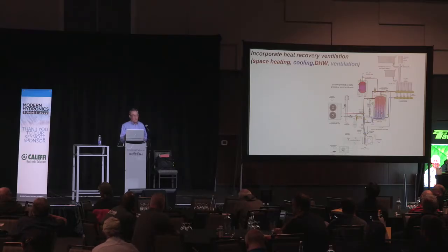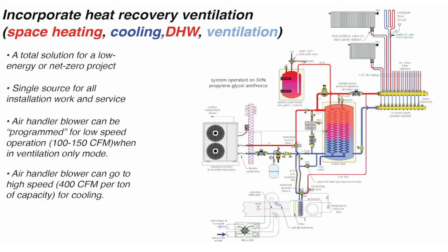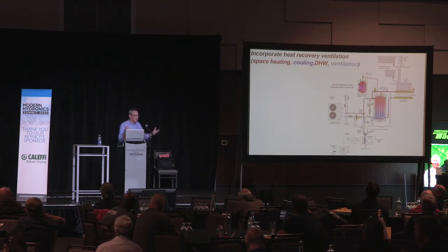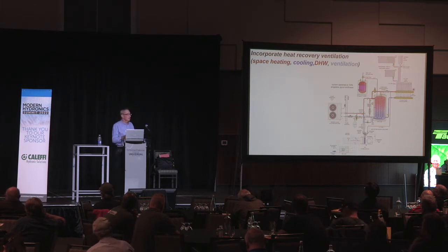The other thing that you'll see over on the far right side of that manifold, and I'm a big believer in promoting this, I always like to see at least one extra connection pair on a manifold station. So five years from now, maybe they might say, well, I want to add a towel warmer to this bathroom. You've got the connections, all you've got to do is isolate the manifold, bring in the PEX to the towel warmer, connect it, and you're back in business. If you don't put those extra connections in, you can still do the work, but it's more work. You've got to drain the system, maybe expand the manifold, tie into the piping. So you can sell the idea of at least one extra connection set, sometimes even two.